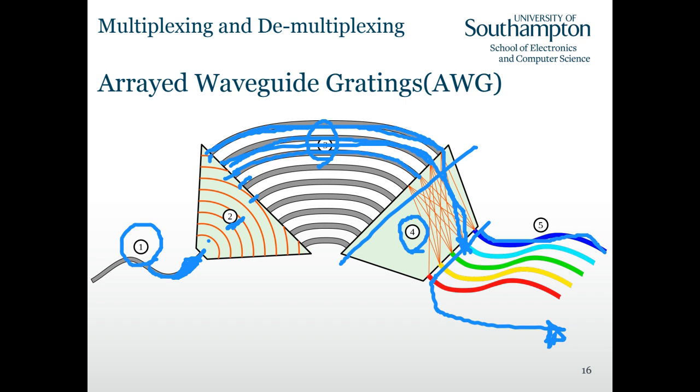One thing to be careful about here is that we do not want spectrum broadening. When a laser creates a signal at a wavelength, it has a linewidth. It's not a single wavelength, it's a collection of wavelengths. So we want this bandwidth to be as small as possible. For example, non-return to zero is better than return to zero because it takes less bandwidth, so that those different colors can be well separated.